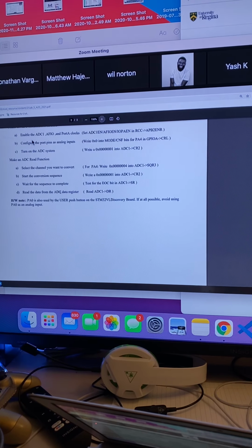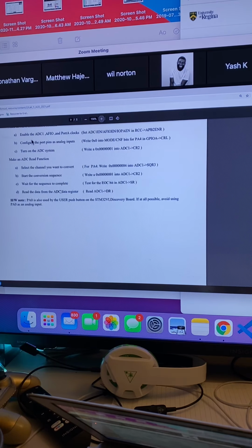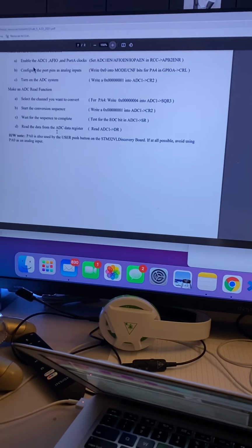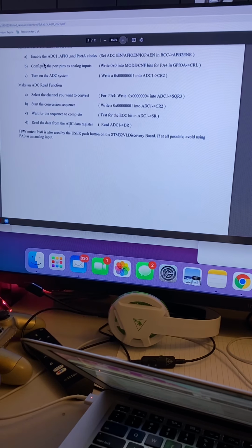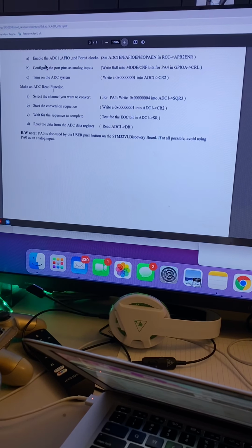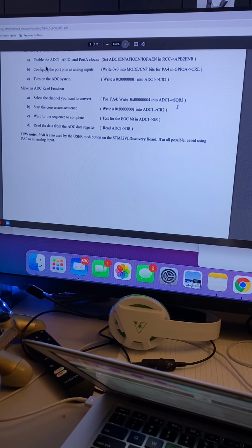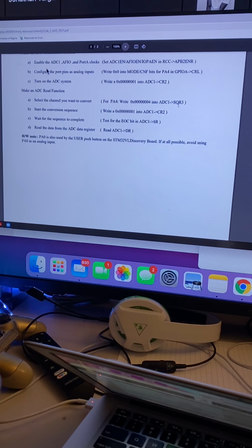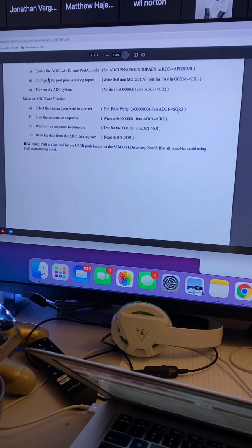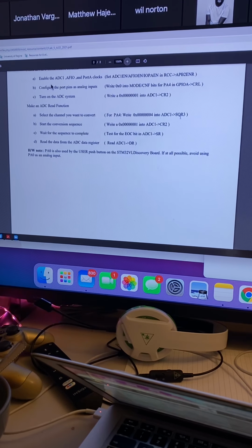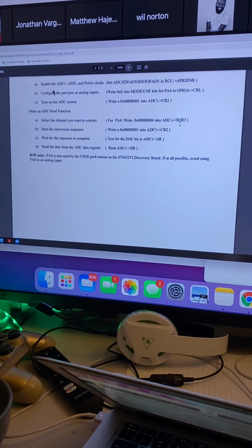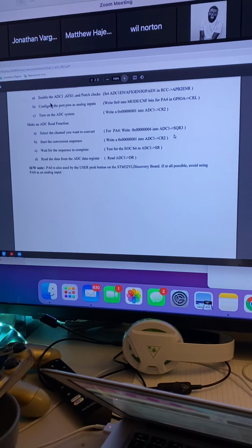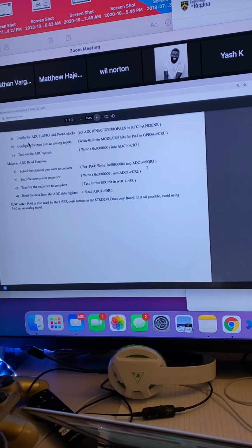All right. Then your function to actually read an analog value, you could write this function in a couple of different ways. In today's lab, we're only using channel 4. So the first thing that you could do is when you call this function, you could just write a 4 into the sequence register because we're only ever using channel 4. Now, if you're using analog signals in your project, you probably have more than one analog sensor. So what you need to do is get the value from one analog input, then go back and get the value from another analog input. Like I say, we're going to set this up to do it in sort of the simplest possible way.